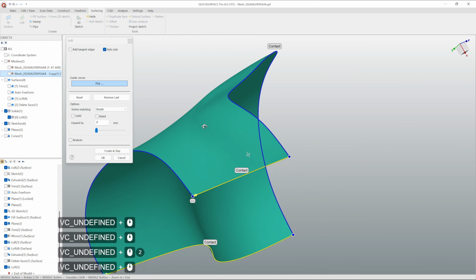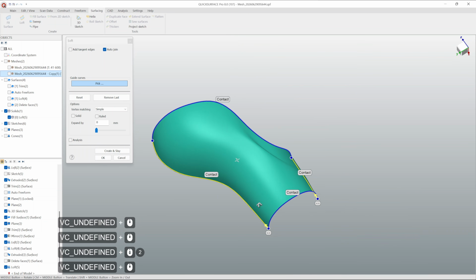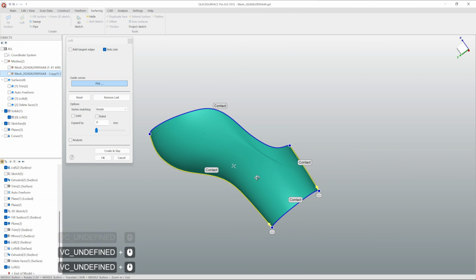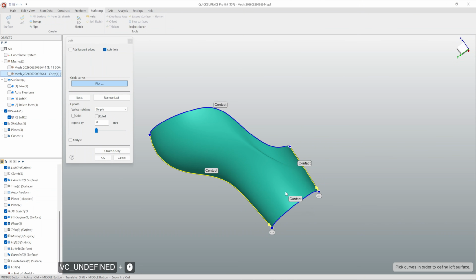all these weird issues. And this is the reason because all of these surfaces are calculated based on, let's say, divide this curve in, for example, 3 or 4 segments, and the same with this one. And later, middle guide curves are being averaged based on all of this geometry, basically average from this curve and average from this one.